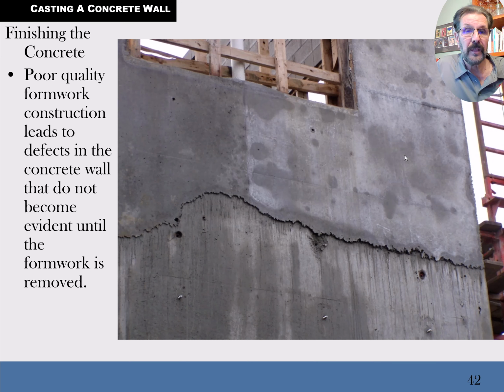More pictures in here. Here's a bit of a screw up here where the form somehow let loose on a repour or on a slip forming, and it didn't quite clamp like it should have, as tight as it should have, and they end up with this excess line. Well, you can come back and patch those walls up to parge it up to hide that difference. So as long as you've got some white glue, maybe as a concrete fortifier, when you buy it already pre-mixed with water, you can spray or mop it on the wall, and then once it's dry, maybe 15-20 minutes later, you can then patch and parge a concrete mixture on that surface with some rubber floats or some rubber gloves, with a sponge or a rag, and kind of smooth it all out and make it look pretty.